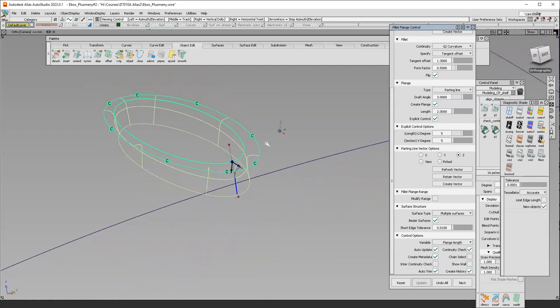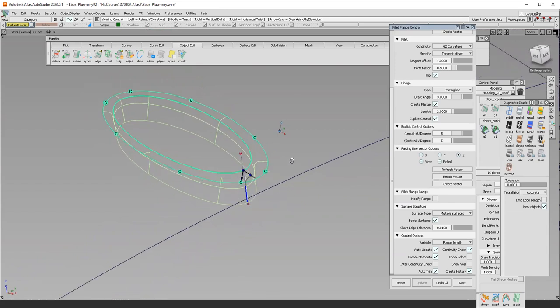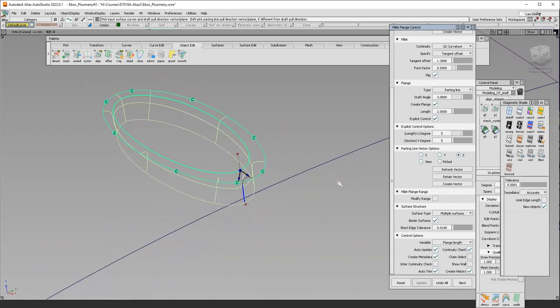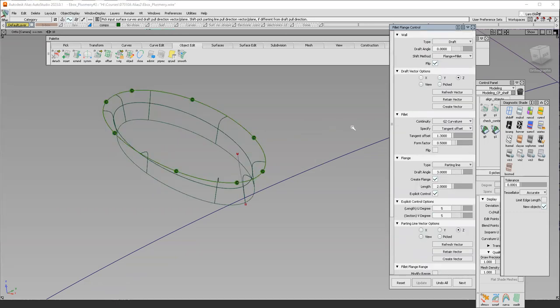And for Class A surfacing, we often prefer to use what is called Bezier surfaces like that. That's a slightly different math from NURBS, but it works beautifully. And it reduces the number of different spans. And this, to me, looks quite all right. So there isn't much more we need to do with this, really.